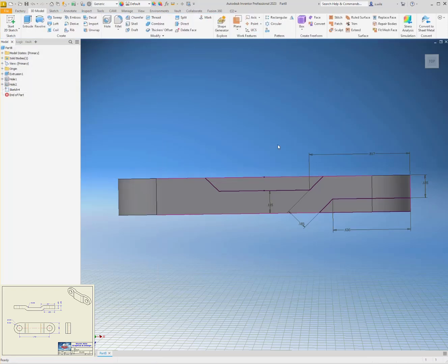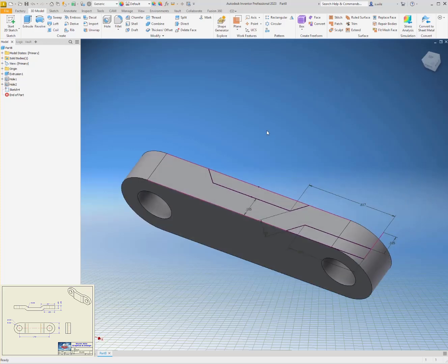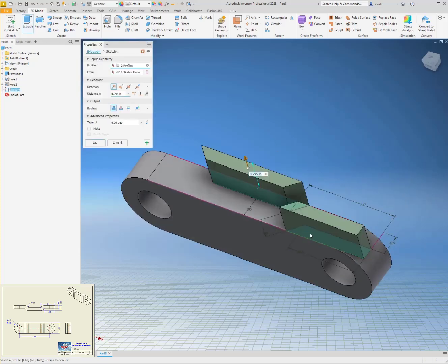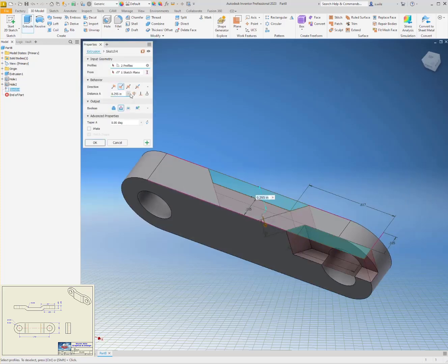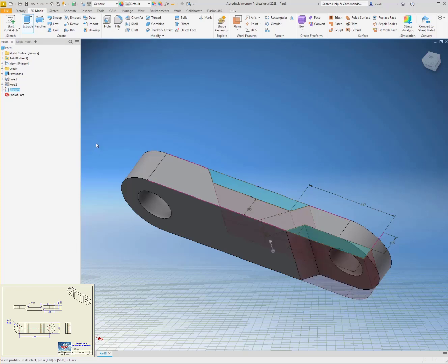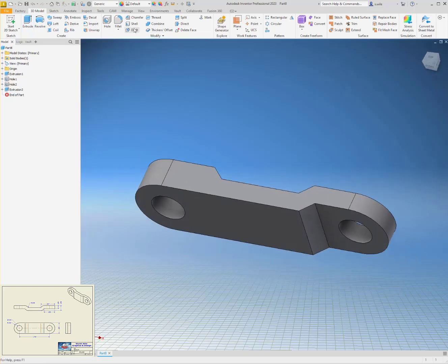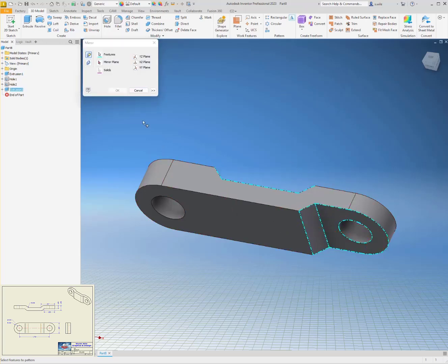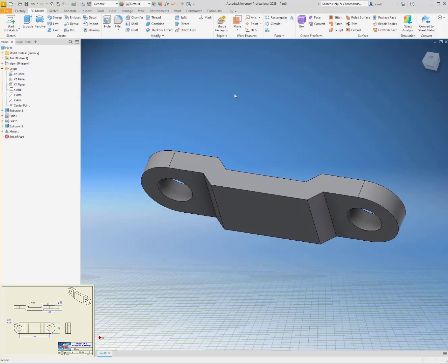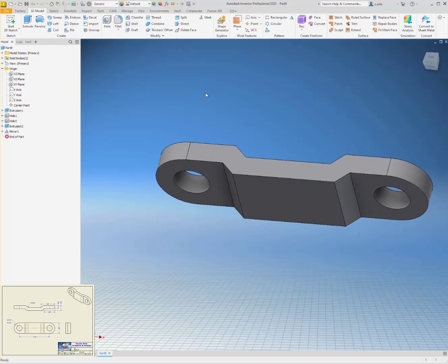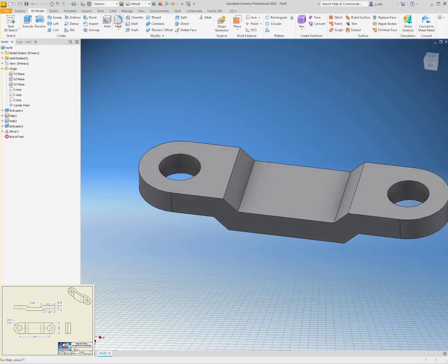All right, finish sketch. Let's see, extrude. We'll say through all. And then I'm going to mirror that to the other side. Quicker than trying to constrain all that additional geometry. 0.03 on the inside fillet.